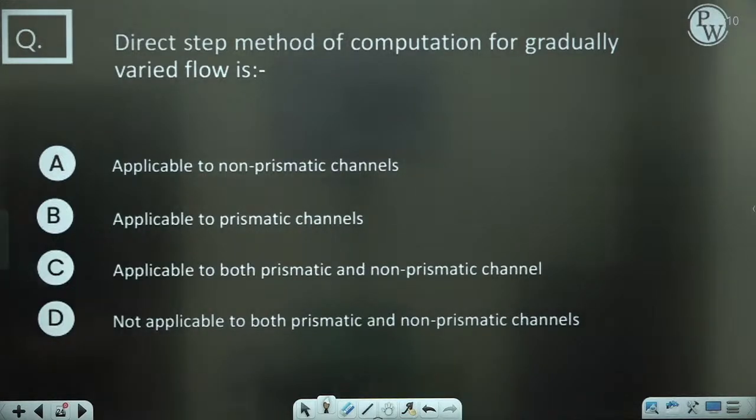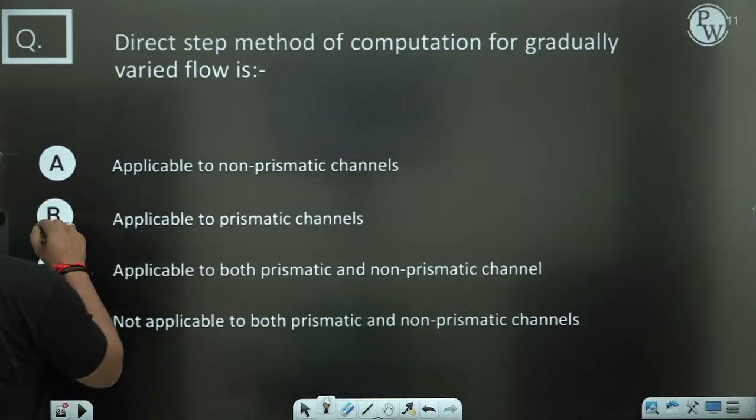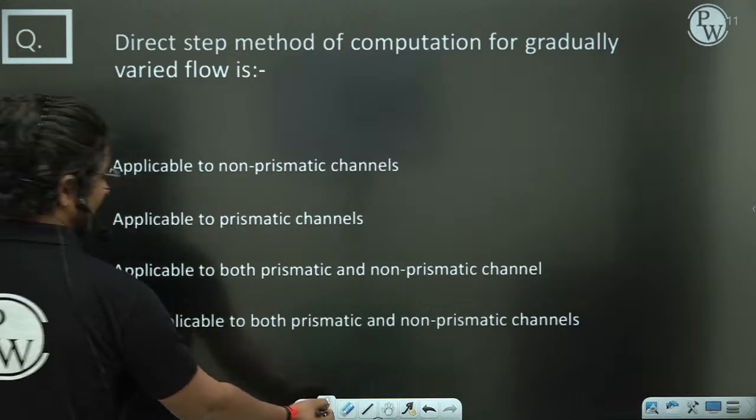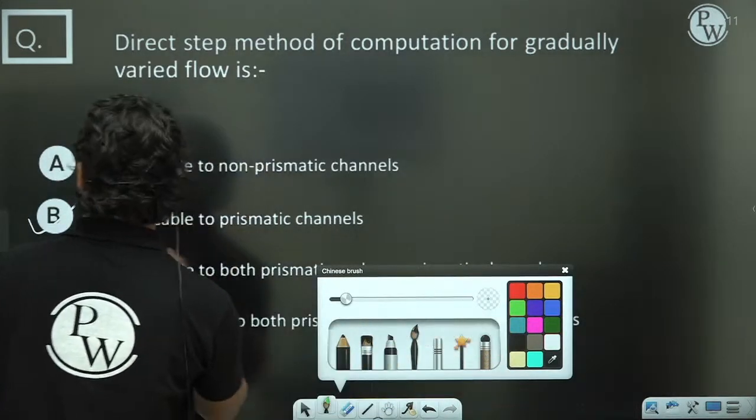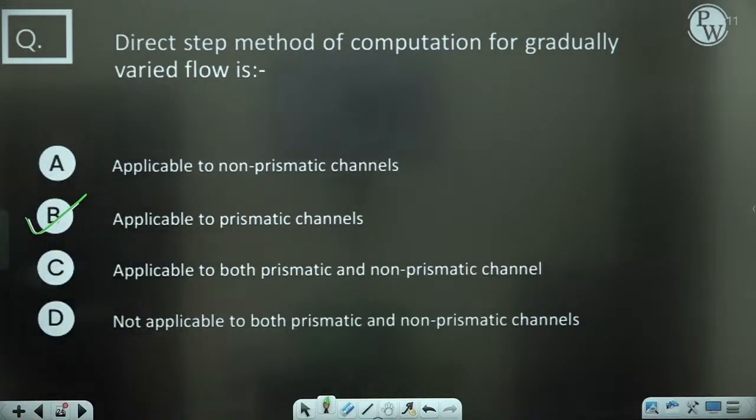Easy question, all of you can answer. Direct step method of computation for gradually varied flow is, since it's a direct step method, only applicable to prismatic channel.